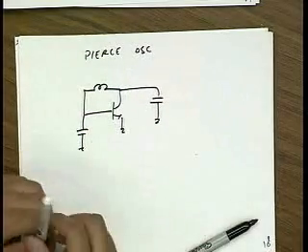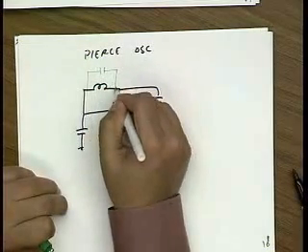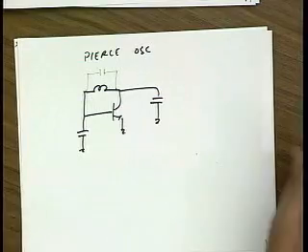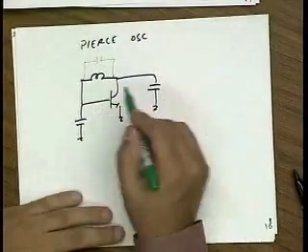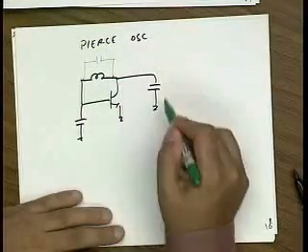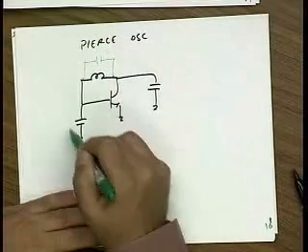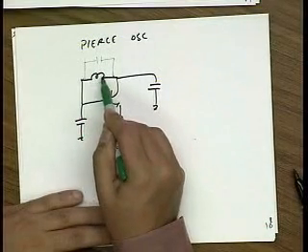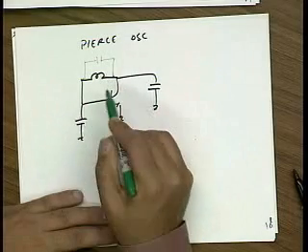And remember, there's also this capacitor across the tank. Well, if you notice, what happens if I get rid of this capacitor? Will the circuit still work? In fact, it does. What happens is that from an AC circuit perspective, you can think of this as one series LC tank, or if you like, a parallel tank with this inductor in parallel with the series combination of these two capacitors.